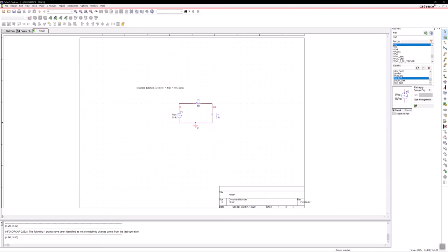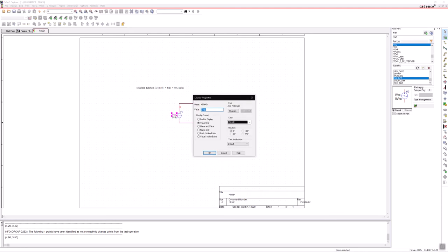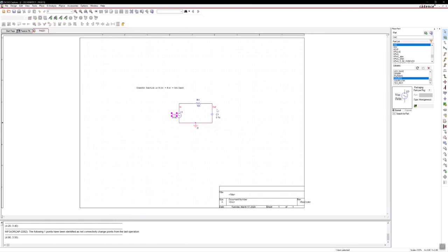But by leaving this at 1 volt AC, now your denominators just become 1, so you divide by 1. So really, the output is simply your transfer function. If I had changed this to 2, then whatever my output is, I have to divide by 2 in order to get my transfer function. So it's very useful just to leave this as 1. We don't want any kind of DC offset, so you leave that at 0.